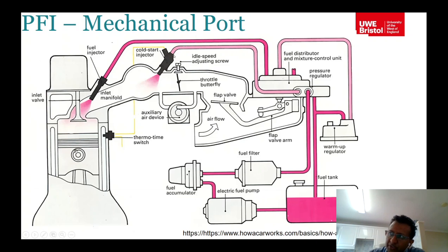So for idle operation, it has another injector, which is called the cold start injector. So it's not actually for idling; it's for cold starting. So when you cold start, this special cold start injector will operate and enriches the air fuel mixture. Thereby you will have a rich mixture, so it will improve combustion or improve ignition initially.